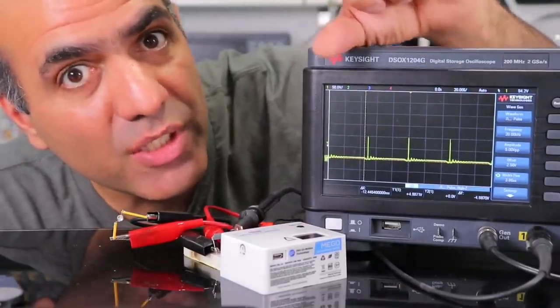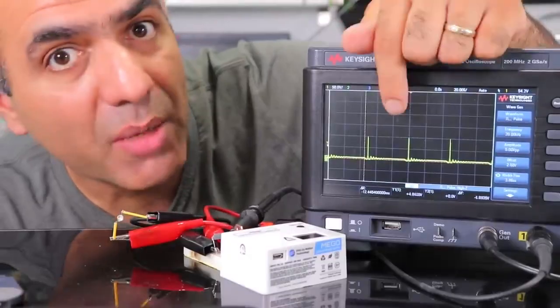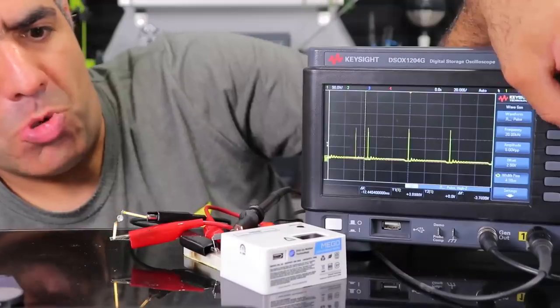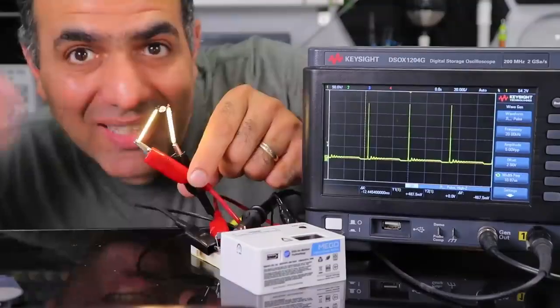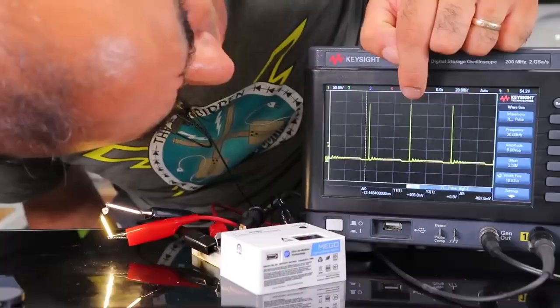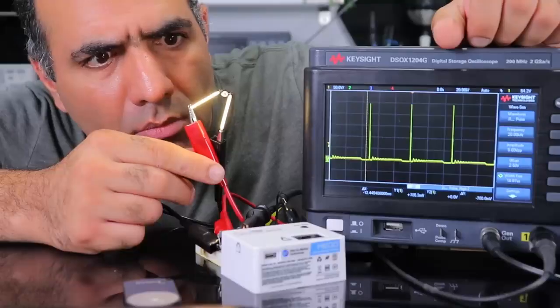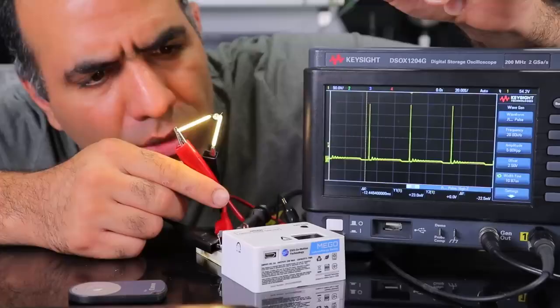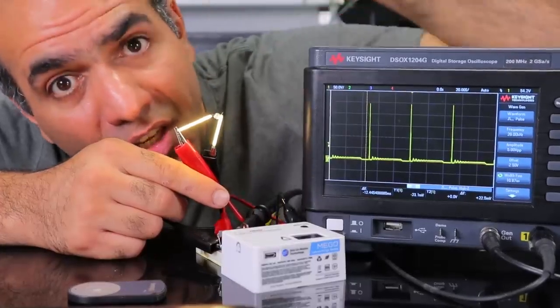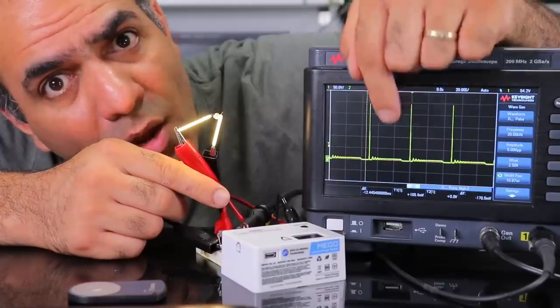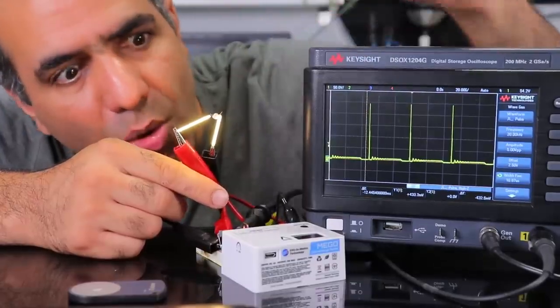But by increasing the duty cycle and the on time, I should be able to increase this voltage. There you go. And my LED string is on. What is that, 250 volts? So I guess there might be spikes of high current through the LEDs, but at a very low pulse width. That's why it doesn't blow up.